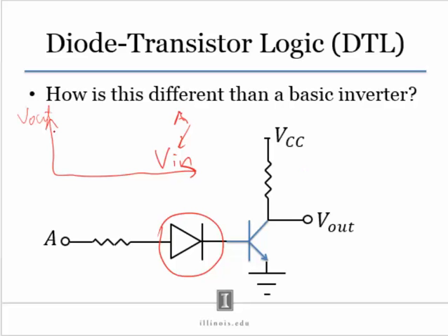Anyhow, if you recall, the input-output characteristic looks something like this: flat, then there's this transition region where the transistor is active, then goes like this, and it would turn on here. The turn on voltage is typically 0.7 volts. Okay. All right, so we could say, all right, until it's 0.7 volts, the transistor is not going to turn on, and we'll have high output.